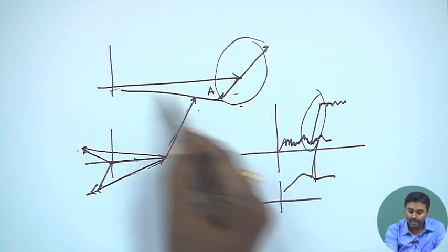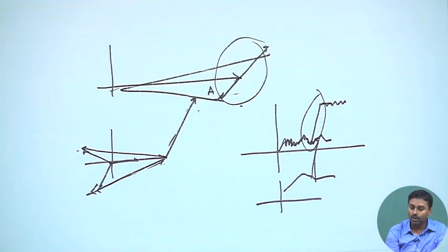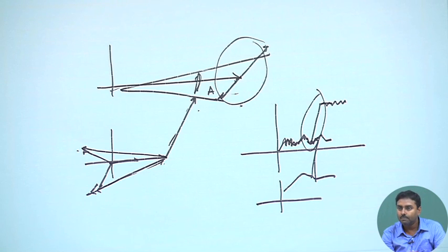Here even if it does a pi shift, due to noise the variation will not be huge, it will just be a small amount of modulation. But in the phase there might be a pi phase shift, so there might be a click noise coming, and these clicks are random in nature. When they come depends on noise characteristics.